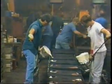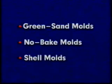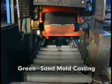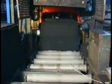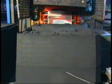Casting in sand molds includes green sand molds, no-bake molds, and shell molds. Green sand molds are made from a flexible mixture of silica sand, clay, and water. The sand is said to be green because of its moisture content.